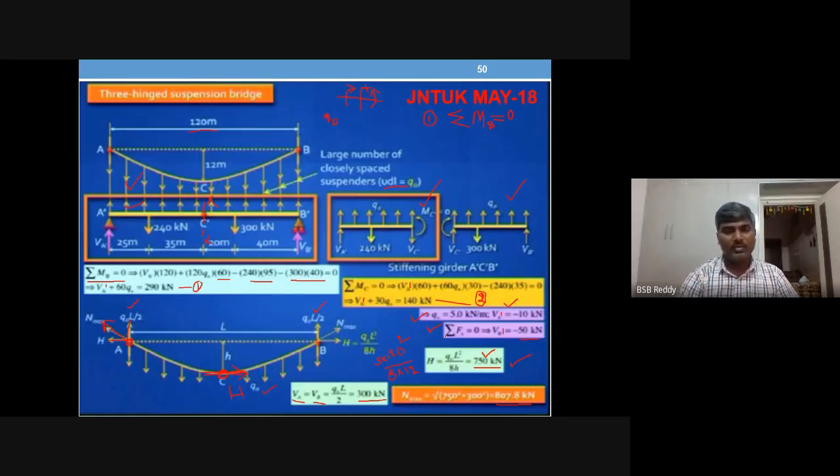So take the free body diagram of the girder first, then apply the equilibrium equation at one end, then take the section at the middle where the hinge is. Take one of the parts which is useful for you, and then write MC equal to 0, solve, and get one support reaction and the Q naught value. Then take sigma Fy equal to 0, and get another support reaction.